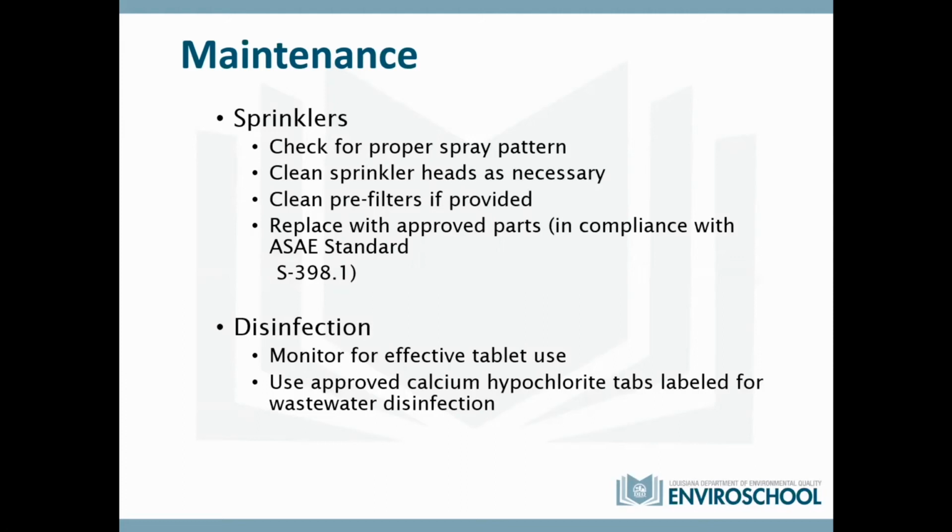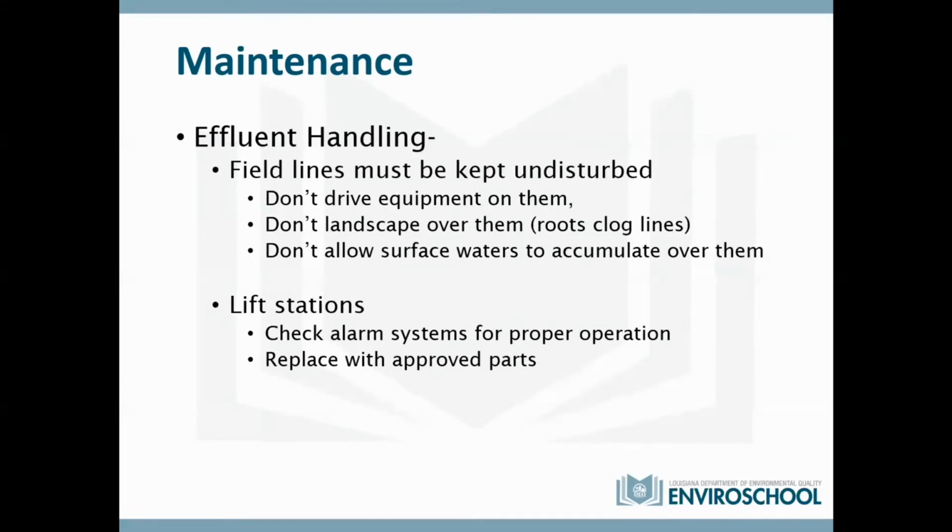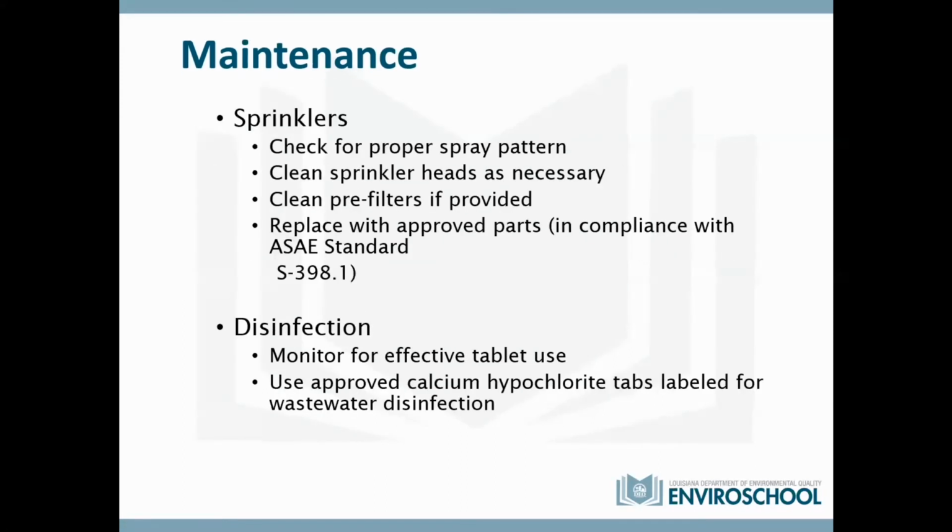Again, these lift stations, sometimes they'll be used for sprinklers. These sprinkler systems, like we showed that picture earlier, look like a nice subdivision with pine trees and whatnot. When they're put in, check out the spray. See what it looks like. Get used to the spray pattern, because if there's any deviation in that, it could indicate something's going wrong.